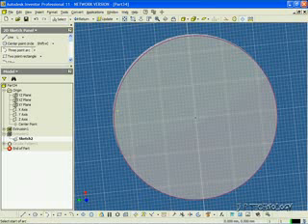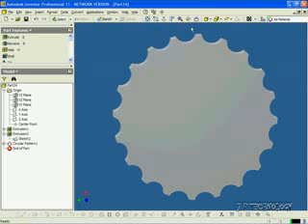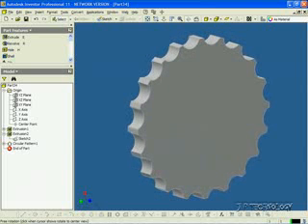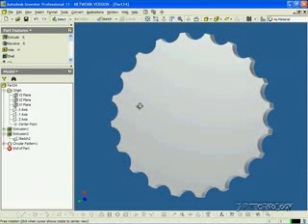Now let's say we want to make a curve cut. So we'll use the 3-point arc. We'll make 1 point here, 1 point here, and then we'll drag this in to cut out a notch. And we're going to have to close this sketch with a line right across, click Update, and now we've cut it out with a different shape. And that shape that we changed on the first feature changes on all the other circular patterns.